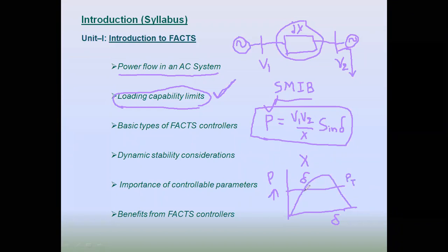From the swing equation, when there is no problem or steady state condition, the swing will be zero, or the mechanical power is equal to the electrical power. Whatever power the machine is getting from the mechanical side, that is the turbine, the same will be transferred to the electrical side. So mechanical power is equal to electrical power, and there won't be any disturbance. Once a fault occurs, for example a line to ground fault, when it is connected to ground, the entire electrical power will be zero. Only mechanical power will be there, so the machine will swing because it takes the mechanical power. So the speed increases, the machine is accelerating, and then once it is cleared, it decelerates, and again whether it comes to a stable state or not, that we'll discuss.